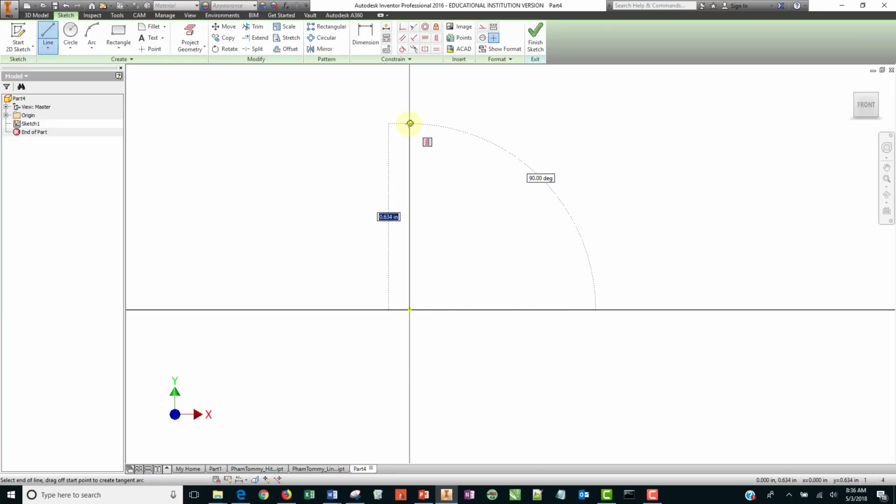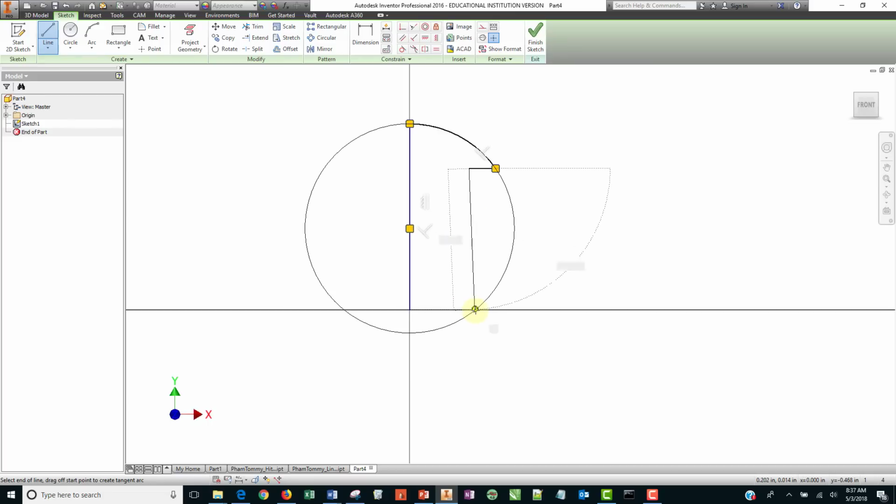So we're going to go there to about 0.65, click, and now I'm going to use that trick that we often forget about of making arcs using the line tool. So I'm going to click and hold and move in a direction. In this case, it's the right direction, and let's see what happens. So click, hold, and it makes an arc. And if I let up on the left mouse button, it completes that arc. Come back a little bit, left click, and then continue on there, and then back home.